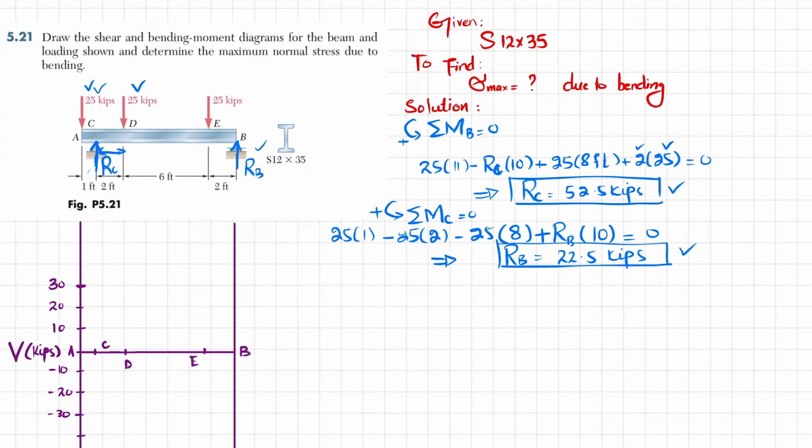You can plot them in order to find the shear force diagram. So let's move towards the shear forces. Now at point A, we have a load of 25 kips. So we have 25 kips. I will also plot it.